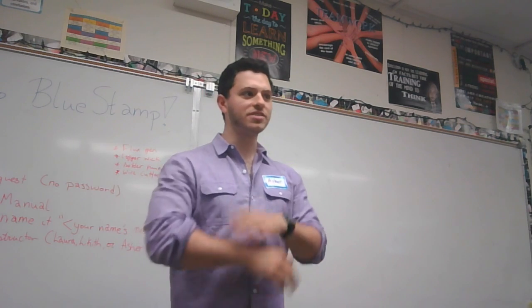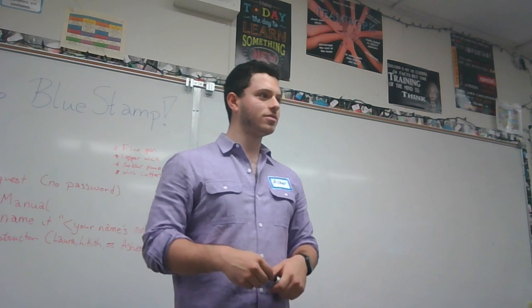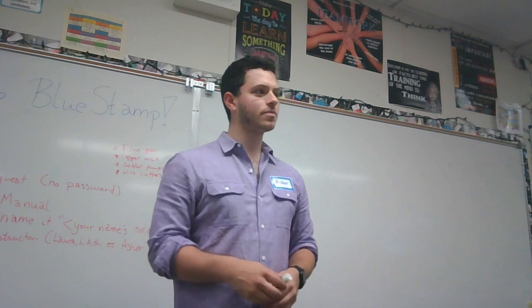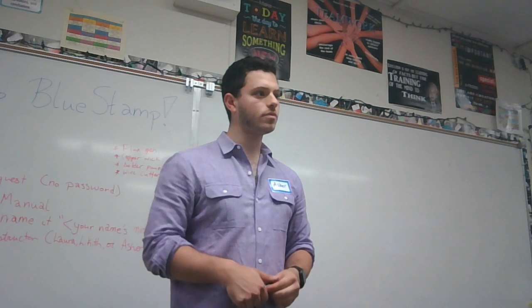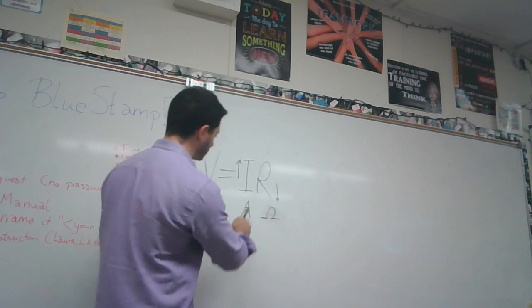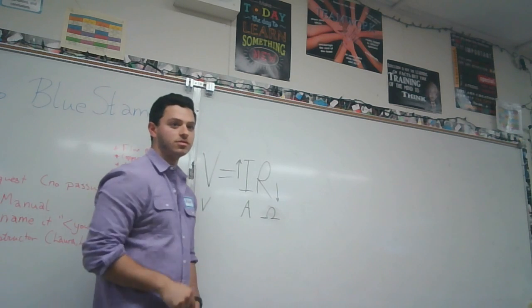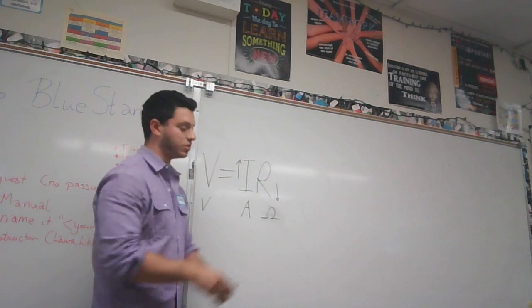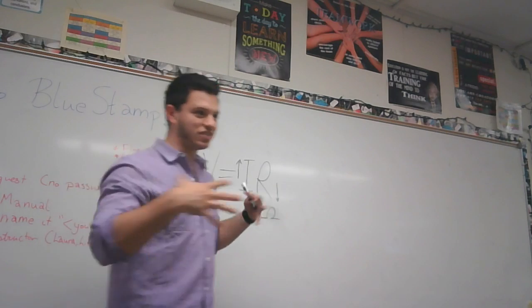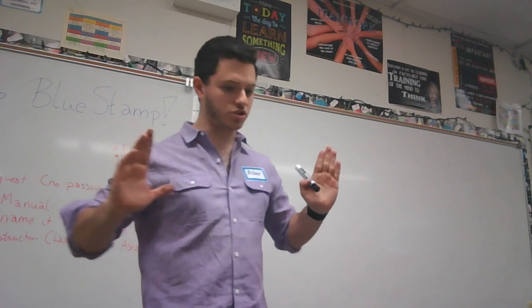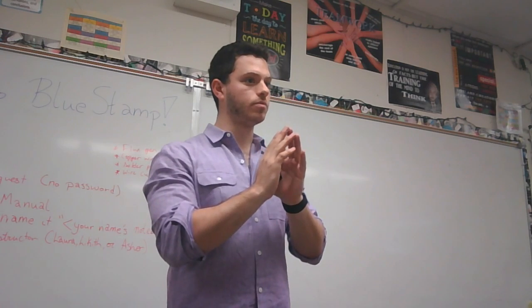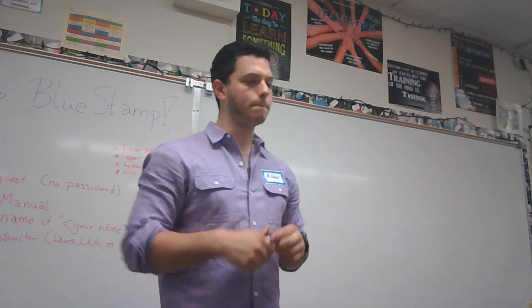Cool. Nobody has any other questions? Yeah. When you increase the resistance, how does that affect the other thing? Yeah, so if you increase the resistance and you were to keep the voltage the same, what's going to happen to your current? Decrease, exactly. So think about the door again. If I have the same amount of pressure, but I increase the resistance by changing the door to be smaller, I can let less people through. Exactly. Yeah.